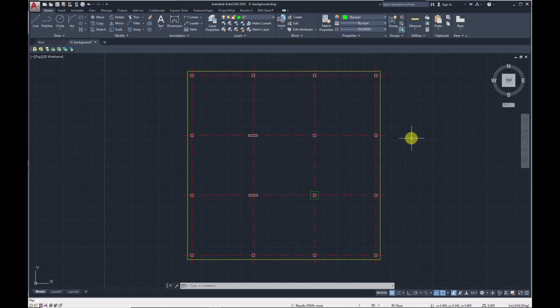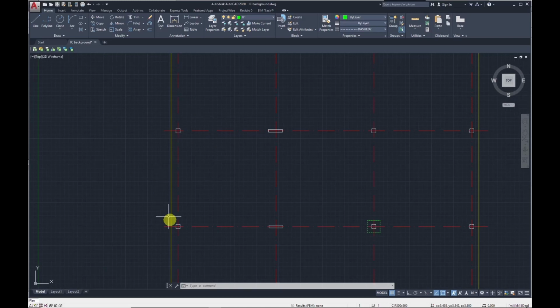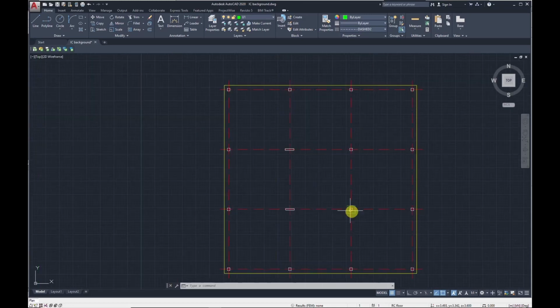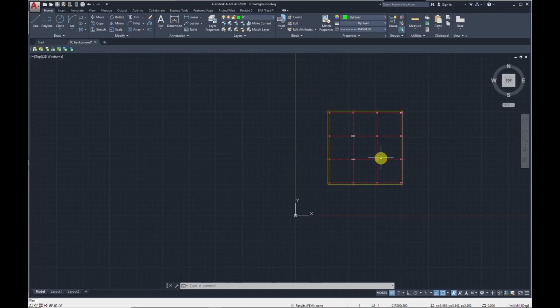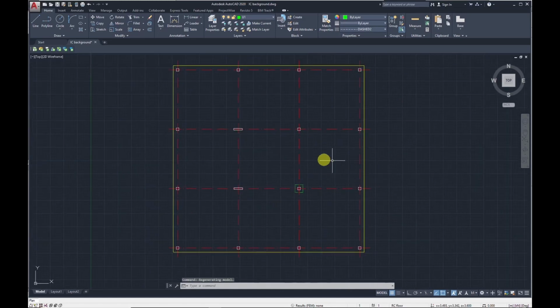So within Robot, I can actually define these and use them to construct my model. You can see I've got my columns. In this instance, I put them in as squares and rectangles, just because that's, in practice, likely to be what you actually have. The dotted green line that you see there is what I'm saying is my punching shear perimeter. And again, I'll come back to why we might want to show this a bit later in this tutorial. So that's my CAD model, all very simple, all very straightforward.